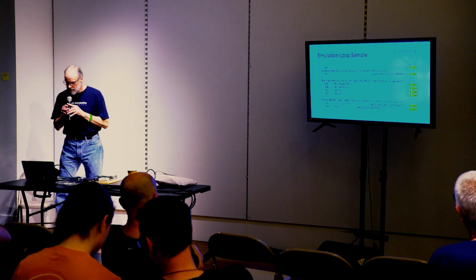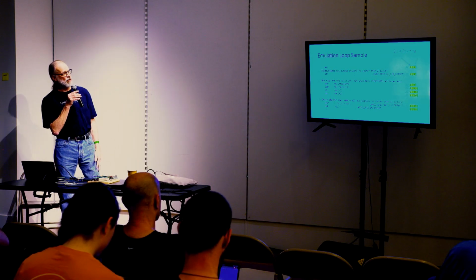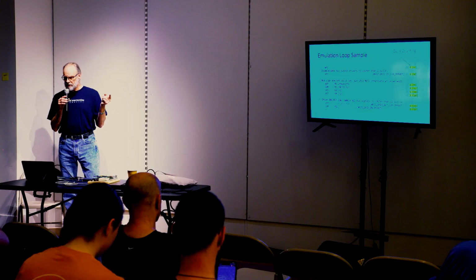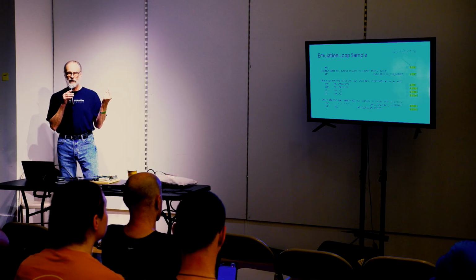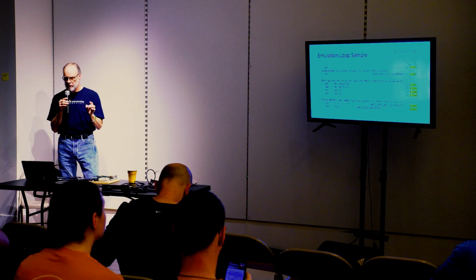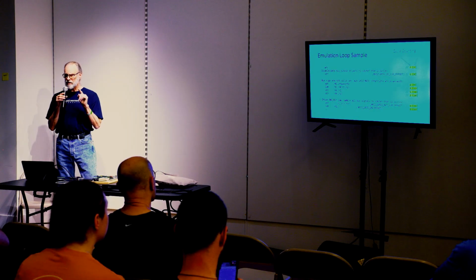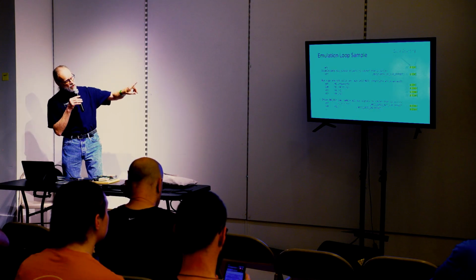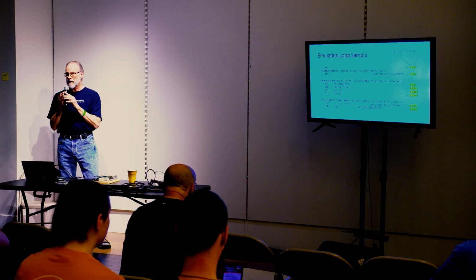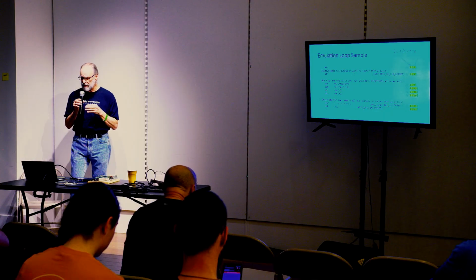Well, I don't know if you can see that, it's too small, but the takeaway there is that you can see the accounting on the far right of the screen. So the WFI instruction takes 7 to wake up, which means that by the time it's woken up, 7 cycles have gone by. The disabling of the output bus drivers takes 1 cycle, so I count that as 1 cycle, and now the running total is 8. And you just go on and on and on, tracking it like that. And now you see what I mean.